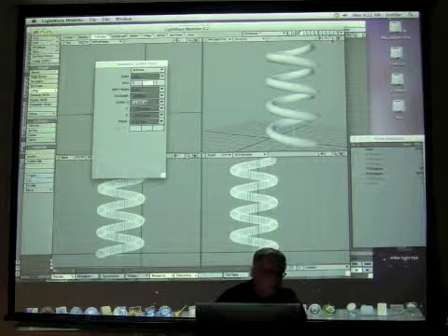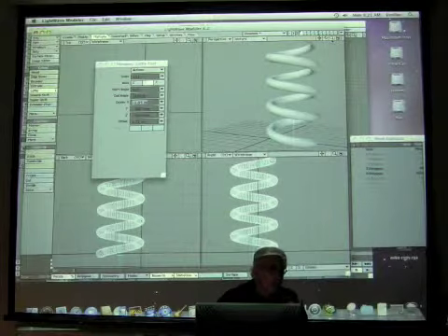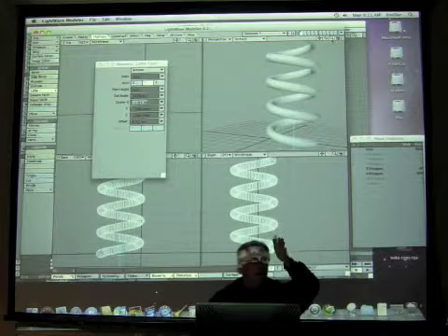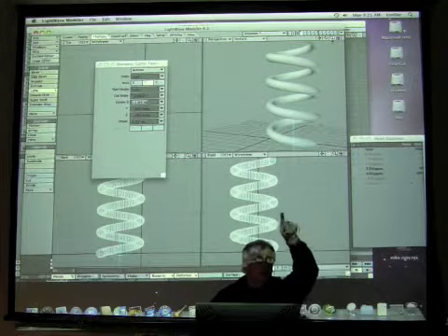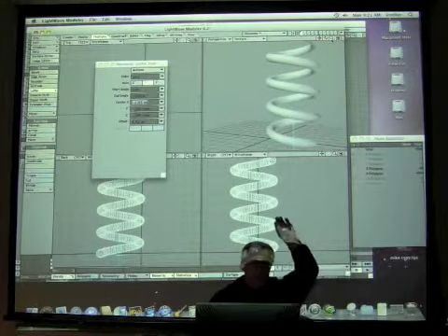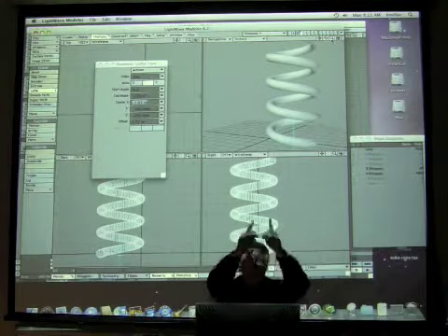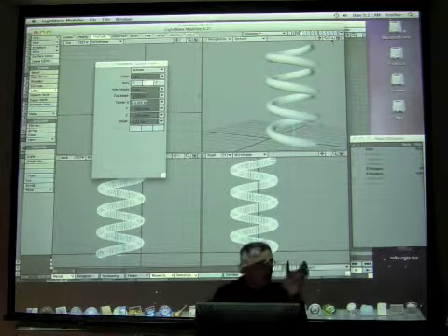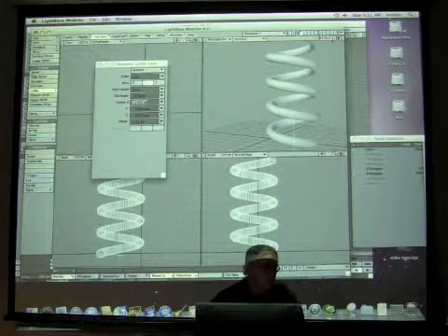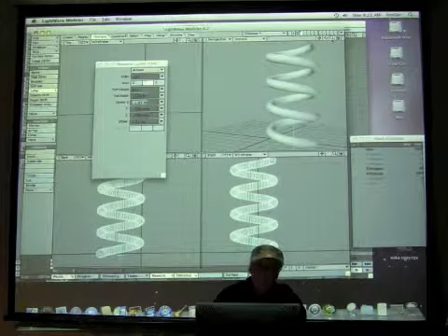We could use the Bevel Tool, which we'll probably use later when we start to use organic modeling to build something like that. It would also be possible to use the Lathe Tool. All you have to do, from the center to the outer perimeter, is create a silhouette, maybe in Illustrator, using a simple path to create that shape. If you're looking at the bottle, it's just half of it. You take that half, that simple silhouette, and then you lathe it, and you have your bottle. So that would be another way to do that. Not too many people use that anymore, but it is a valid way to work.